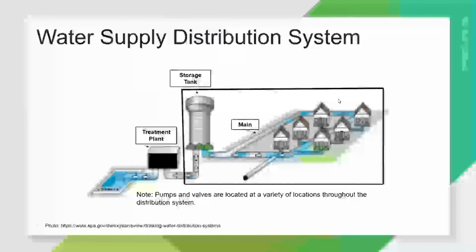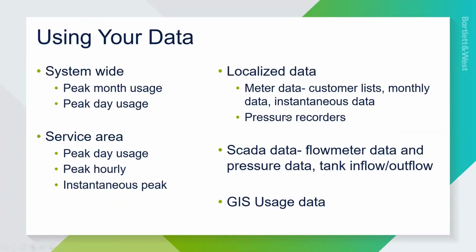And every system has data. Every system has system-wide data, whether it's SCADA data from your treatment plants. Figure out a peak monthly usage, a peak day usage. Again, you can go service area by service area and look at the peak month usage, the peak day usage.